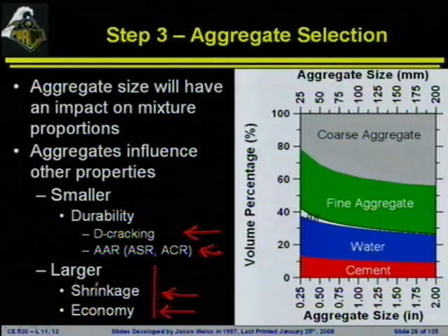All right, so all other things being equal, the size of the rocks makes no difference on shrinkage. However, larger aggregates allow us to use less paste. Using less paste will reduce things like paste-related problems and will reduce things like shrinkage. Somewhat clear? I'm sure it'll be confusing by the time we get to the end of the semester.